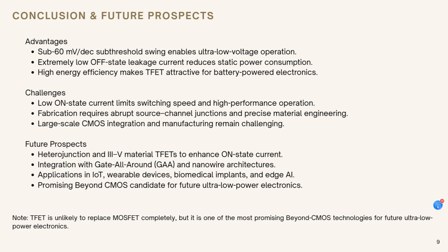However, TFETs still face several challenges before they can be widely adopted. The biggest limitation is their low on-state current, which restricts switching speed and makes them less suitable for high-performance computing applications. In addition, TFET fabrication requires precise material engineering and abrupt source-to-channel junctions, making the manufacturing process more complex than conventional CMOS technology. Achieving large-scale integration while maintaining consistent device performance also remains a significant challenge.